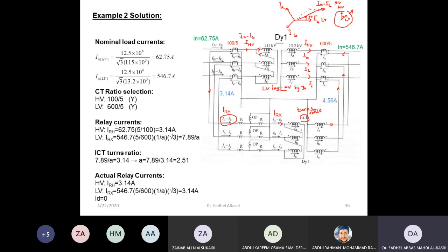So while choosing, what I want is this current to be the same as this. So I'll connect this to delta star. And the delta star, as you can see, this is IA, which is in phase with this. And this is IB, which is in phase with this. And this current will be, if this is IA and this is IB, IA minus IB also.